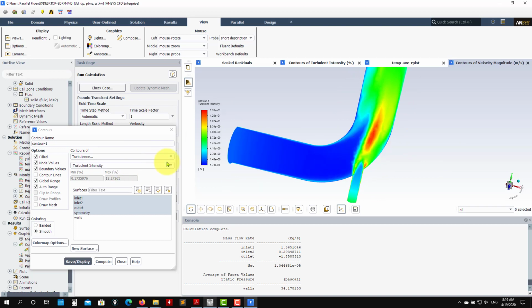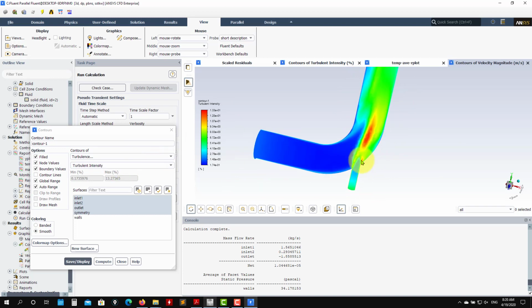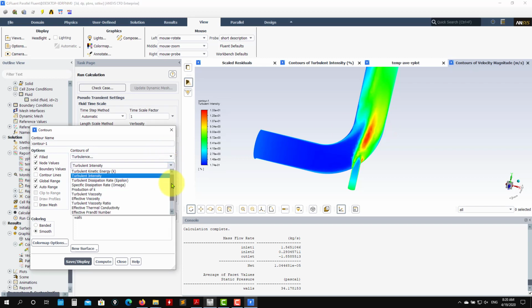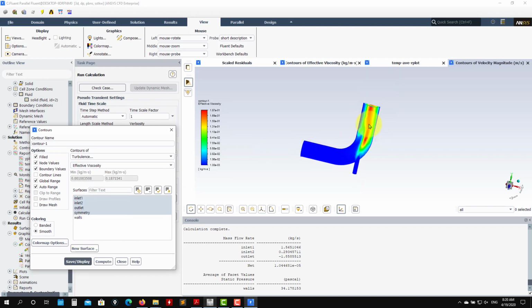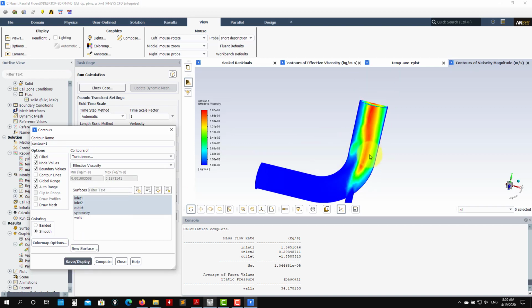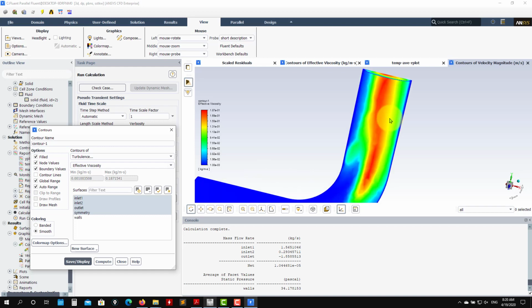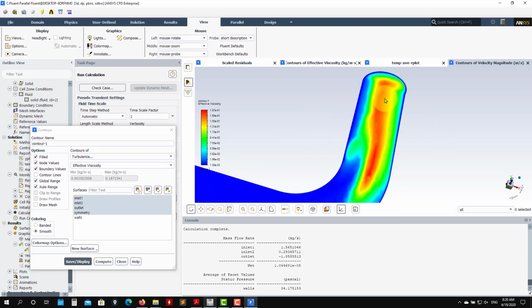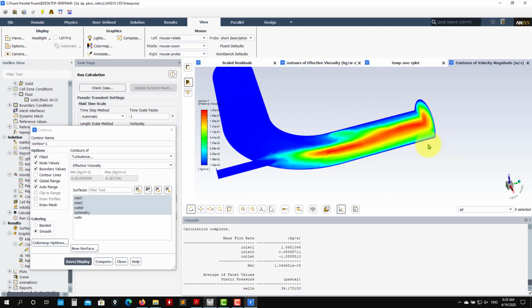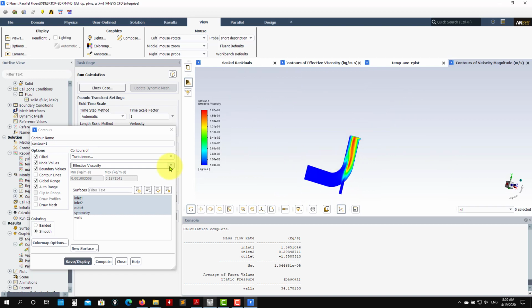Okay, but instead, I don't like this. It can be misleading. This is telling you where the turbulence model is kicking in. But if you want to get that information, maybe look at the effective viscosity or turbulent viscosity. Here you have the magical quantity. The turbulent viscosity is the one that is adding the shear stresses, increasing the mixing and everything. So you get more information from there.